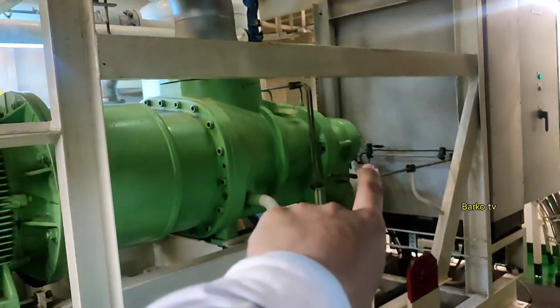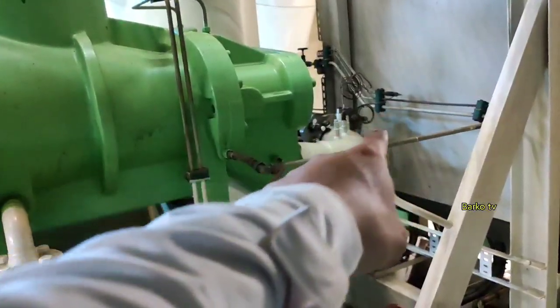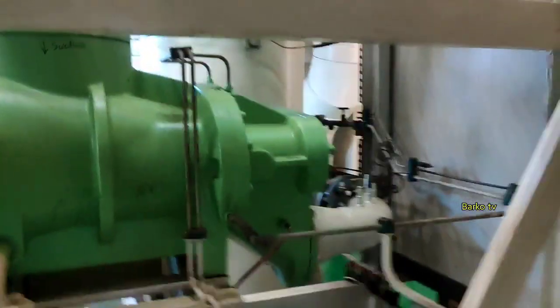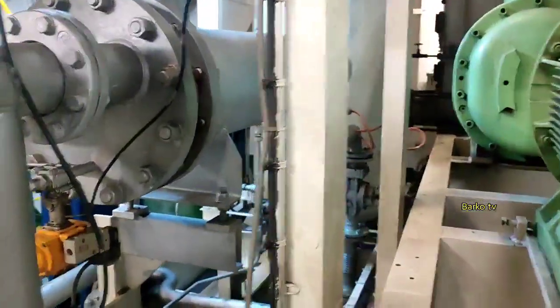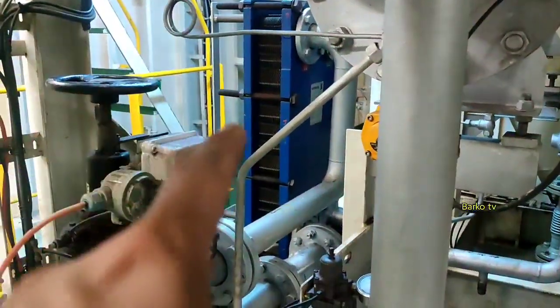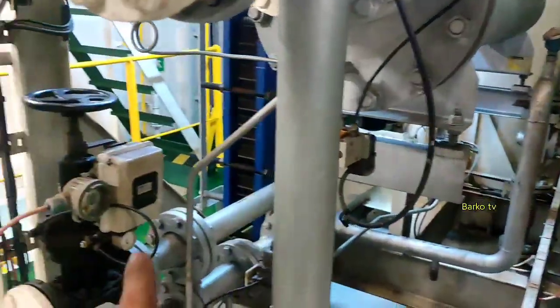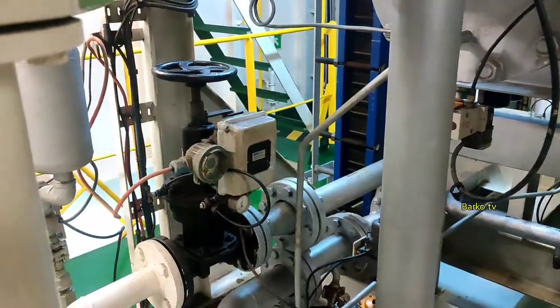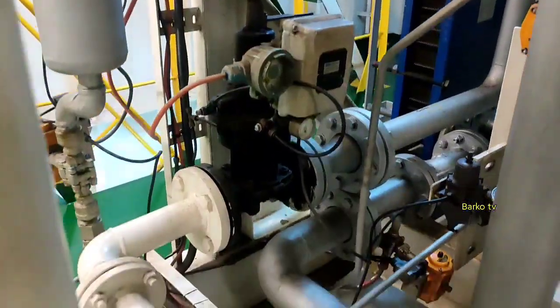The compressor starts at 65 and up inlet lube oil temperature, so that you can run this compressor with an on-load signal. If that's satisfied, okay, it's good. That is a cooler, that is the lube oil part, and this actuator at the seawater part, which controls the temperature.